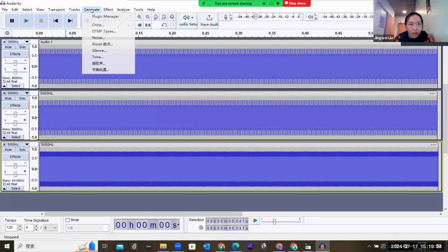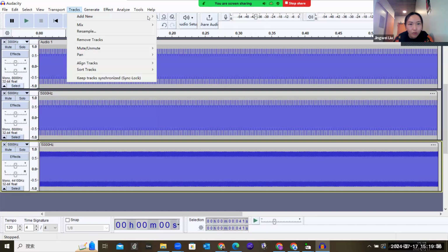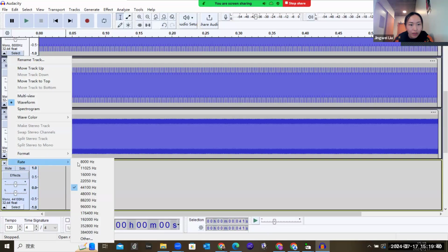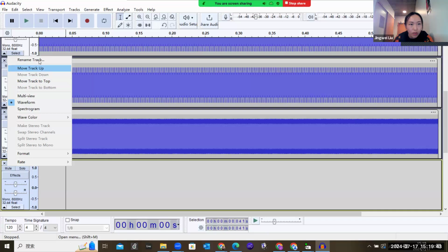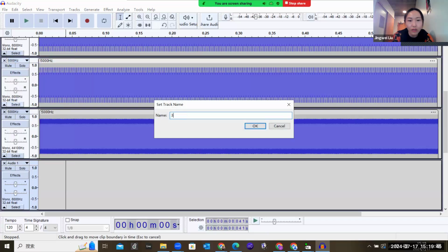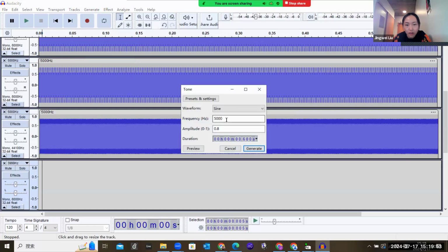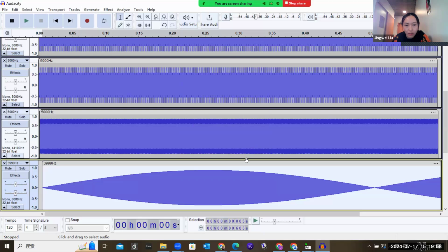Let me add a new track and change the rate to 8,000. And like what he did, let me generate a 3999 Hz tune. Just generate tune, change this to 3999, generate.